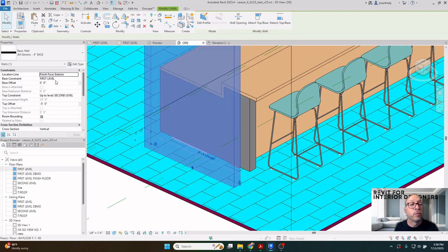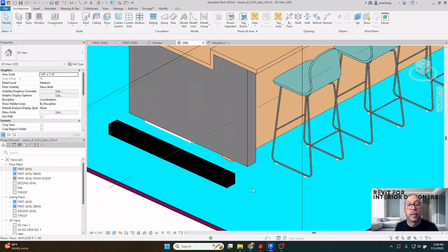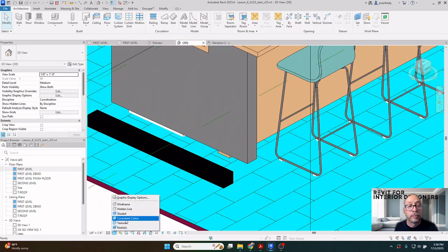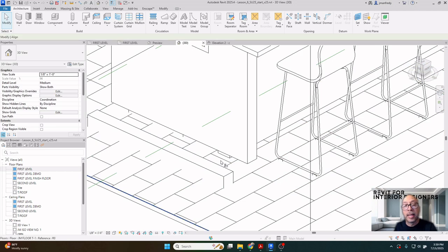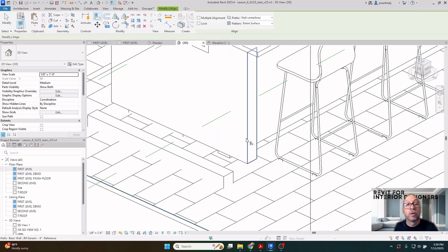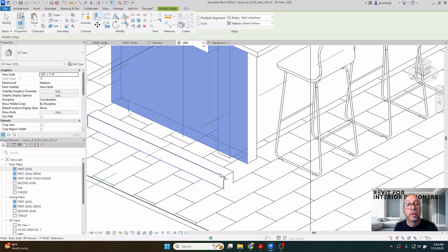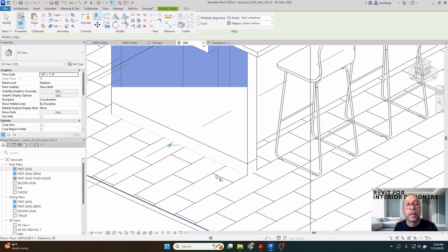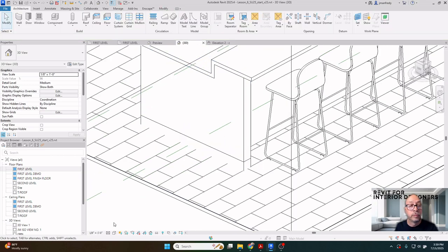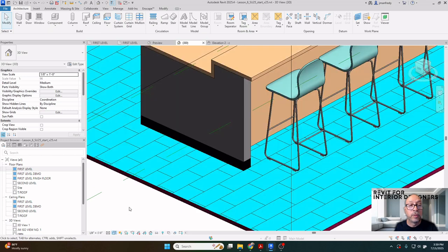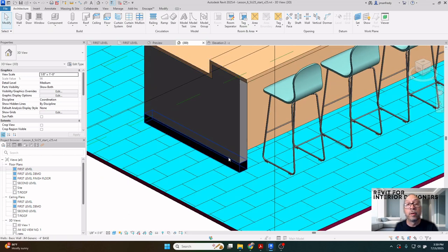I'll make sure here it's 4 inches tall, so it goes from the unconnected 4 inches tall. So that's fine. And now I will line this up. I'll line the face of this with the face of that. Let's do this in black and white so I can see what I'm doing. Align, AL. Go to this surface here, with this surface here. And it pushes it right under that wall. So now, in shaded view, I can see that there's a base below that wall.